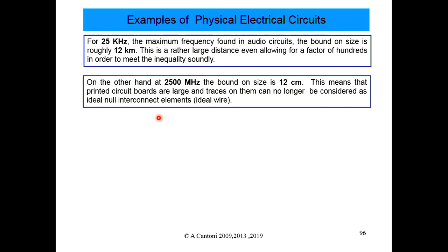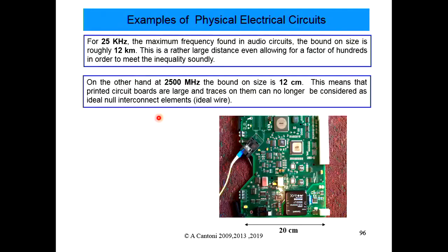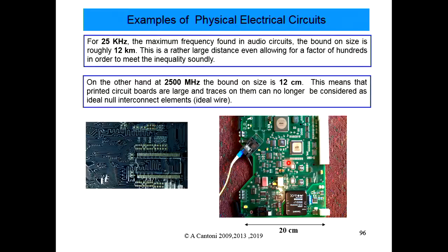But if we look at, say, a printed circuit board, then it's a different story. The board's height might be a few centimetres or less, and then the actual wire traces between the different components can't be considered to be small. You have to take into account the delay and also all the other effects that come along with it, which we'll talk about.